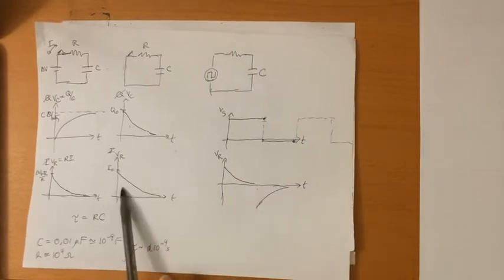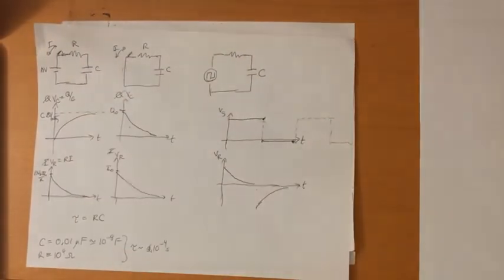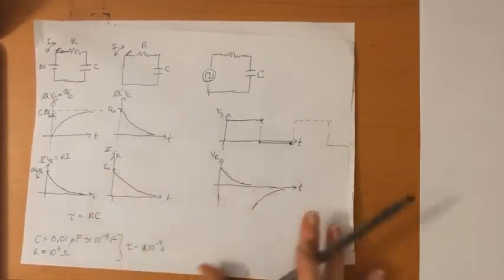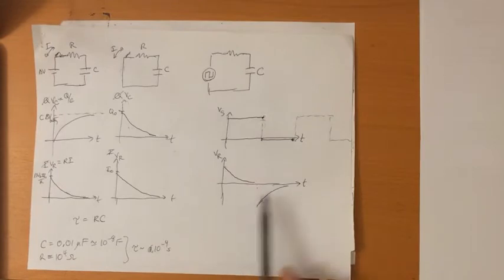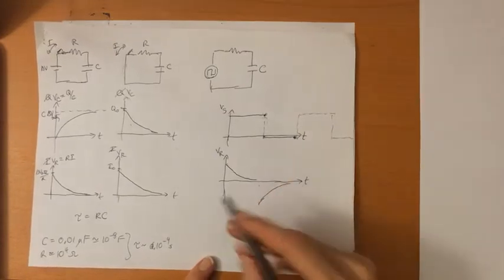When I talked about the current here, I kind of assumed a direction for the current, which was this way, because after all, this is the way it would move when it was discharging. But the way we hook up the oscilloscope, this is actually going to show up as a negative voltage. So that's why that's actually flipped upside down like that.